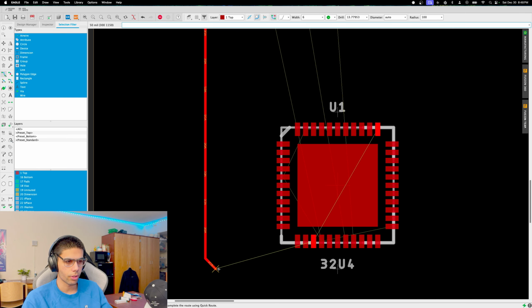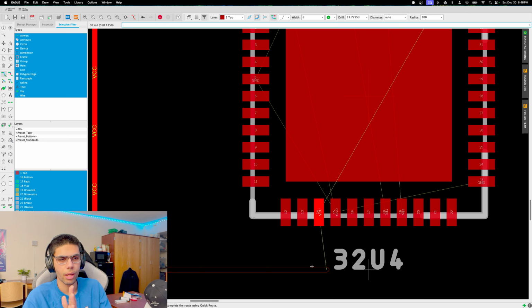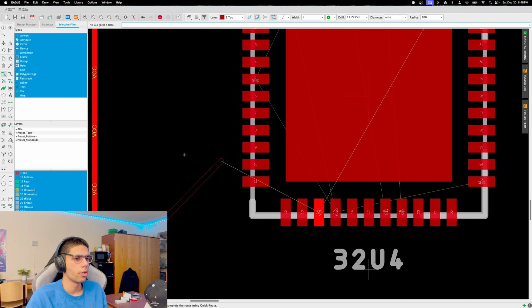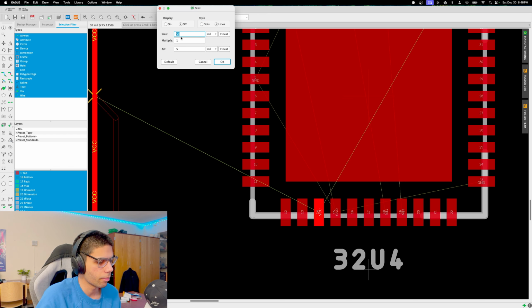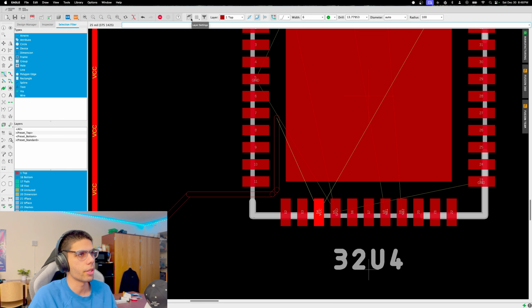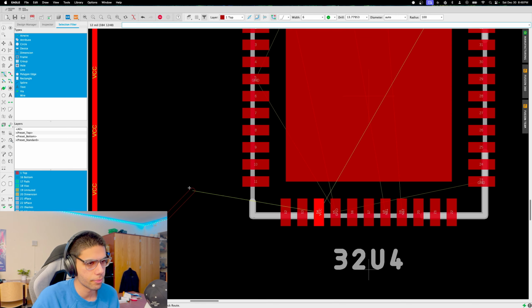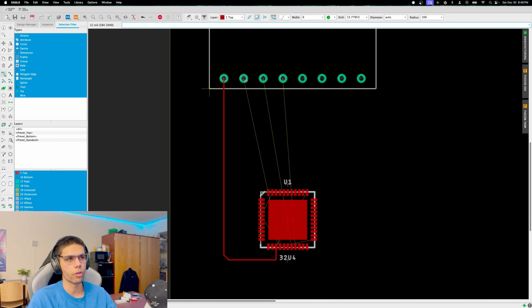If you are not happy with how the connection looks, just go on there again. And you can also change your grid because after this point, it's snapping to just too far ahead, right? So you can change your grid size again. Grid spacing is right here. Make it 25. Now you'll be able to get a finer control. This is also not enough, so I'm going to make it 12. This is fine enough. You can connect it. It's going to snap. So this is one of our many connections that we want to do.